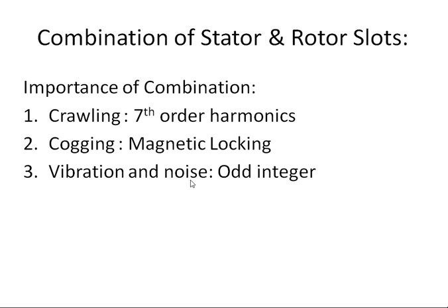So here we are saying that we have two main parts of the three-phase induction motor, a stator and a rotor. The stator is the stationary part, which consists of a core having slots in the inner periphery. The slots carry the three-phase AC winding, which produces the magnetic flux when three-phase AC supply is given to the stator. This rotating magnetic field produced by the stator windings is linked by the stationary rotor, thereby inducing EMF in the rotor according to Faraday's law of electromagnetic induction.